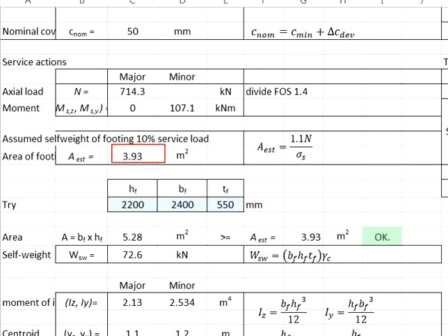This gives us a guide that later when you need to propose the size of the pad footing, the total contact surface area to the soil should be greater than this 2.93. Having the contact surface area less than this is likely to fail in terms of the stability against the soil bearing capacity.